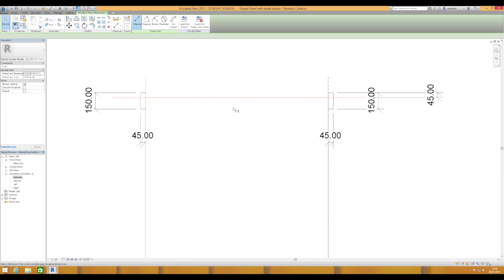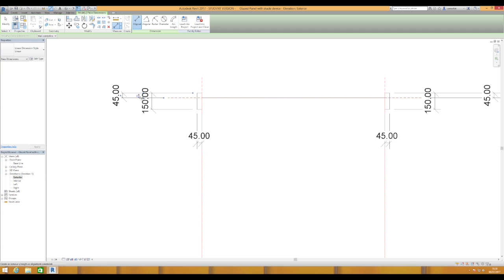So we might have to add the dimension tool once again for here to the top. I'll put it out over there and then lock that so it stays 45. And then the other thing we might need to do is the align tool. Once again AL is the shortcut key for align, or you can use this tool under modify.